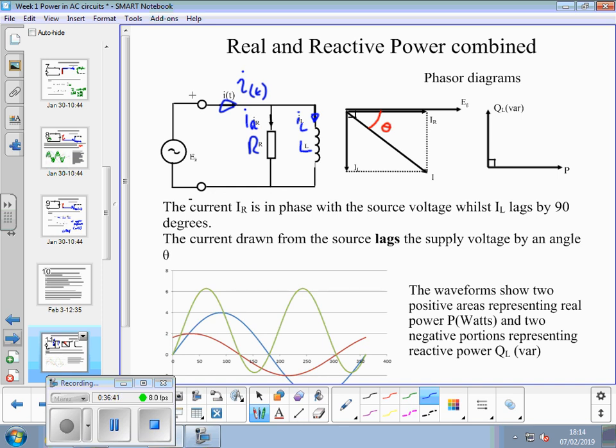Okay, and voltage in blue. So there's the voltage phasor, VG in blue. In this case, you'd say that voltage is the reference phasor, and I'll put that at angle 0 because it's applied to both the resistor and the inductor. So we're holding that at 0.